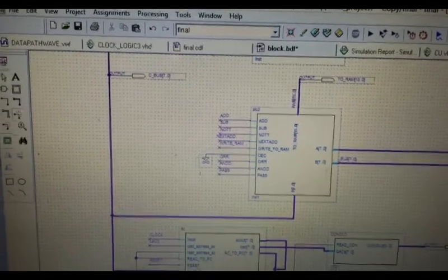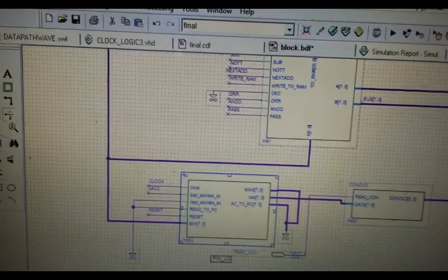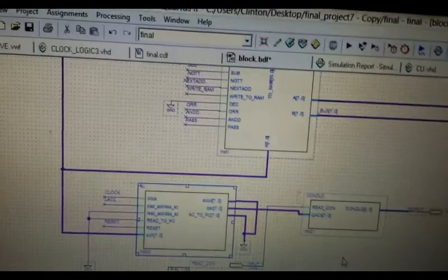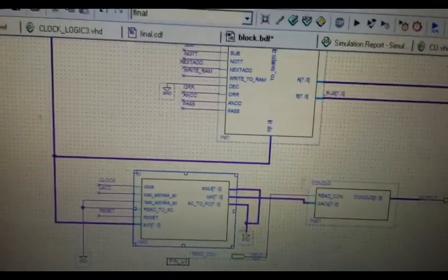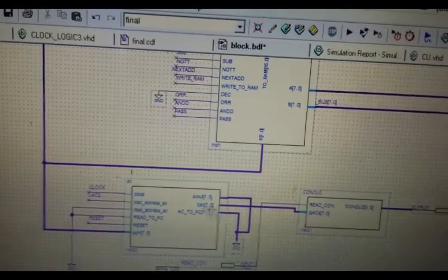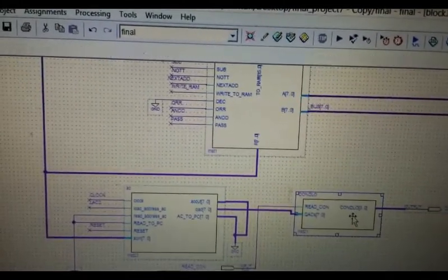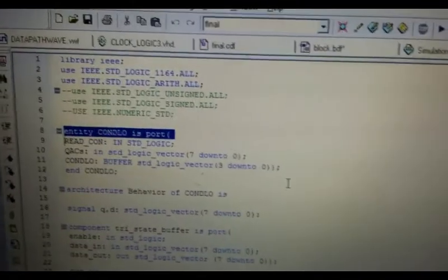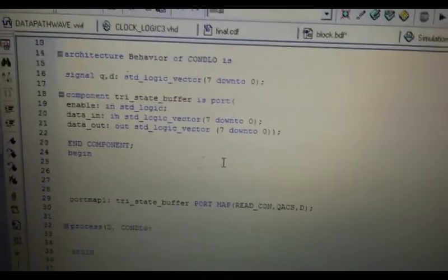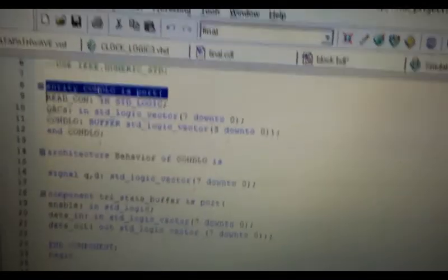But it doesn't really serve that purpose. Some of the inputs are actually grounded. But all it is is just an 8-bit register that loads the value from the ALU, and automatically it will just spit it out to the conditional logic, and the conditional logic, based on the previous arithmetic operation, will provide signals that tell you whether it was greater than 0, less than 0, 0, non-zero. I think that's it actually.